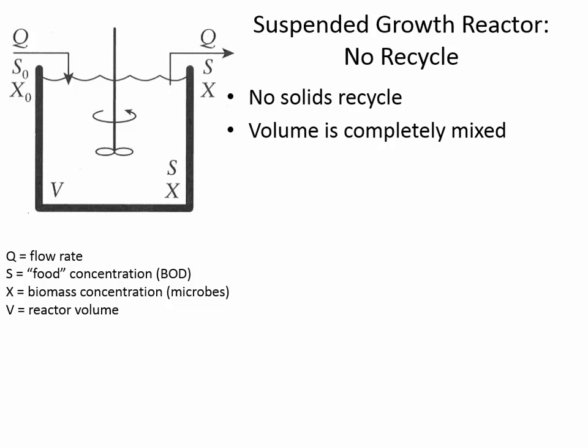It's bad if they eat a lot of food in the river, because then it depresses the dissolved oxygen and will start to kill fish. So it's just best for us to take control of the situation and provide plenty of oxygen and a special place where the BOD can be broken down. This is a schematic of what it would look like if we didn't have recycling of the sludge.